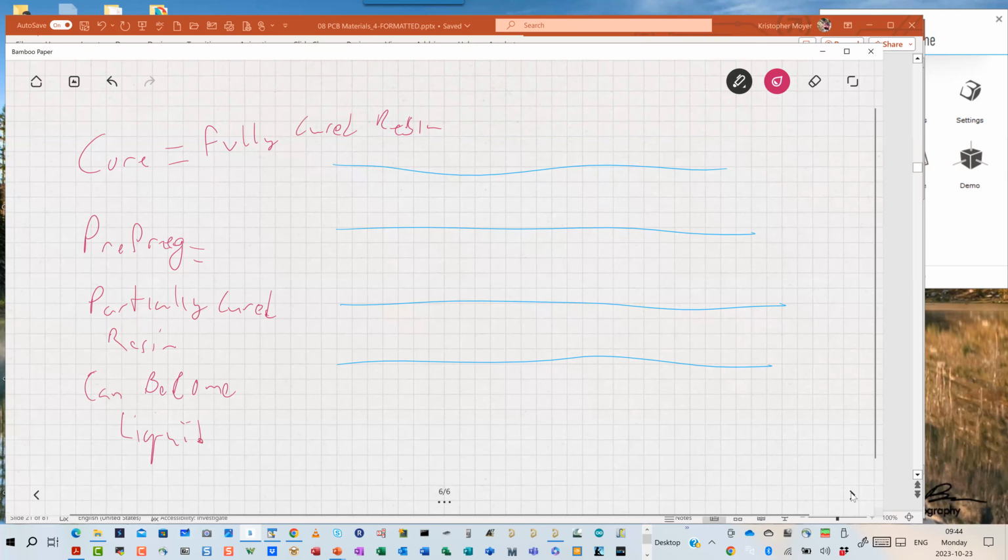Now, if I want to glue these 4 sheets of copper together, first off, and we'll get into this next week in processing, I have to process my layers in pairs. Meaning I can't just glue all solid copper together and then somehow etch all of my traces and features. I have to pre-etch the features on the inner layers, go through the etching or form the traces and pads and stuff. No holes yet, but I have to form the traces and pads and so on on all the inner layers. Then I have to be able to glue everything together and then form my traces, drill my holes, plate, and so on for my outer layers.